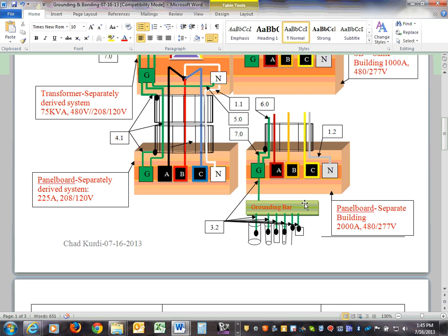That's for reliability, absolutely. Thank you, Dave. That's typically if you have a wood building, a wood structure. That's why in dwellings you end up with two: a rod and a water pipe. They're supplementing each other. So, any comments, guys? Any questions about that? Comments, questions?